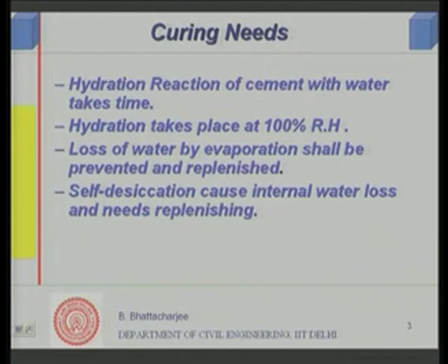Besides, the chemical reaction of cement with water also consumes some amount of water. So, supposing I stop the evaporation process, even then there will be some loss of this moisture due to the chemical reaction of cement with water, because some of the water will be consumed, and that we call self desiccation. It is actually an internal loss of water, and we must replenish this water if the pores have to remain saturated with moisture vapor. So, these are basically the needs.